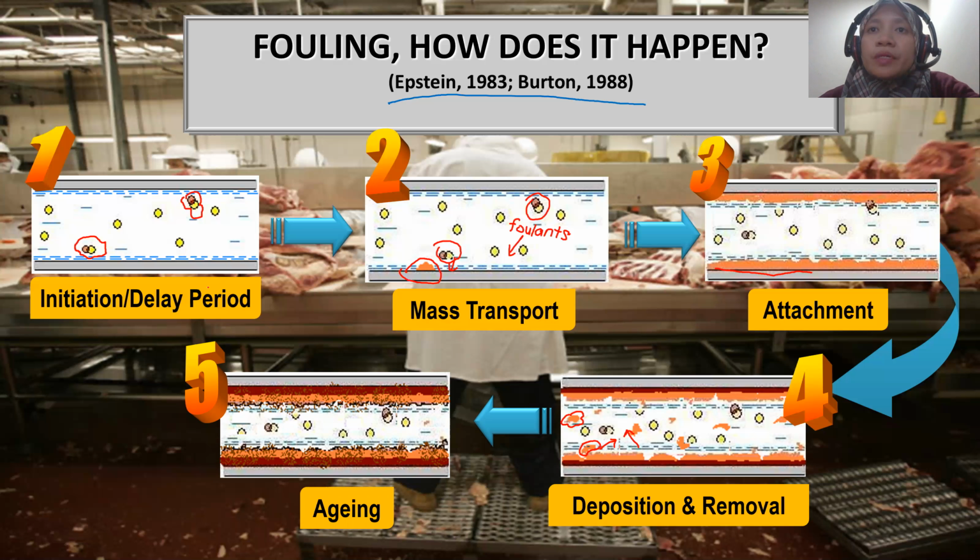So I'm using a darker color here, a different color. You can see here this represents burnt fouling layer deposit. This burnt fouling layer deposit will happen if, let's say, the food processing is not stopped for cleaning. So common practice in food industry is to stop the processing before stage 4 occurs.